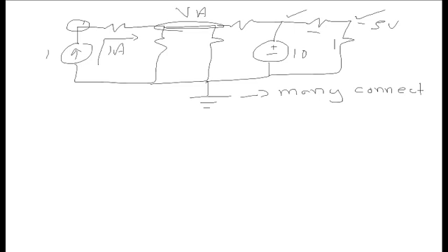My next step is to label some currents. That's 1 amp, as we've said. That I'll have to call I2. There's I3. Through this resistor, I4. And through this resistor, I5. Notice how what I've essentially done is chosen my own directions for those currents. Here's how I did that, although it's not really a general rule. The 1 amp current I know the direction of. I know it's going that way.